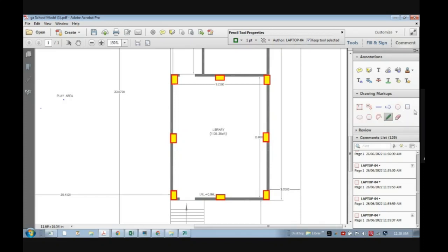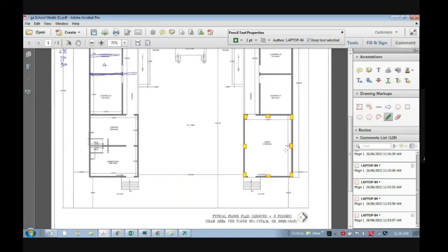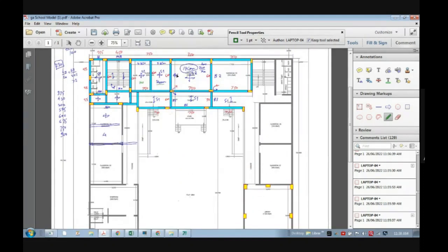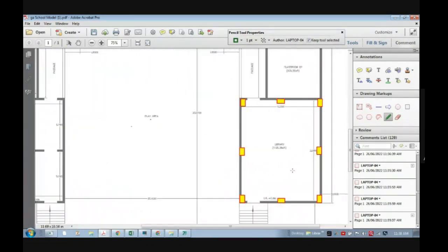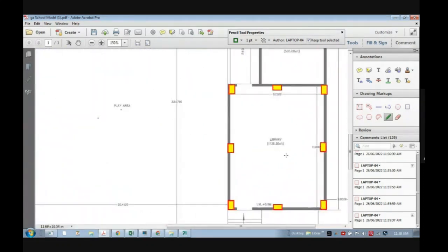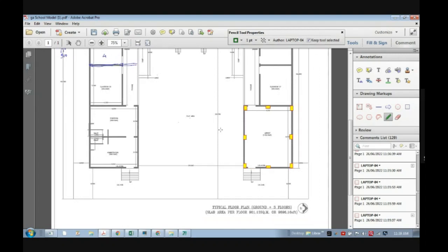So first always try to give the solution with respect to RCC, because let me explain the problem. Why am I avoiding that? The reason is, say in this whole building we have provided the beam, slabs, all columns and everything. Only for these slabs, is it really feasible to get the PT post tensioning system over here? Shall we place a different order and coordinate with the post tension agency and then give the solutions? For one slab, the slab cost also will be higher. So many times you need to take a decision.